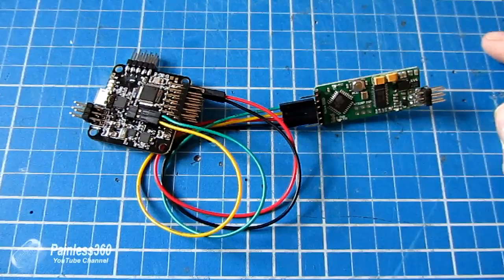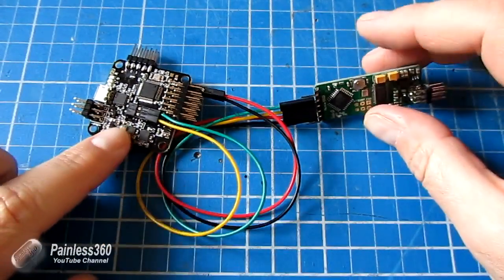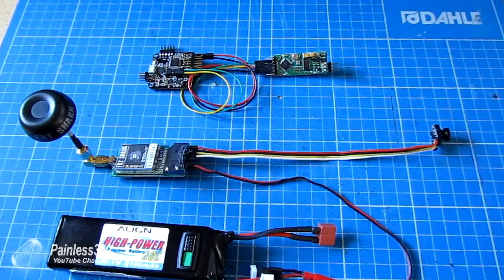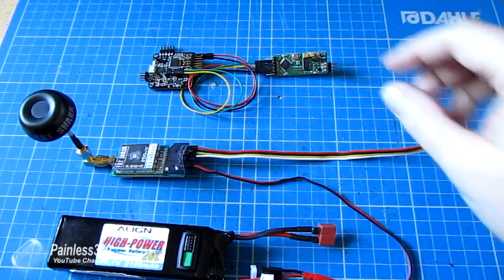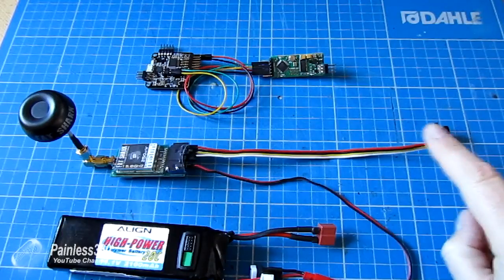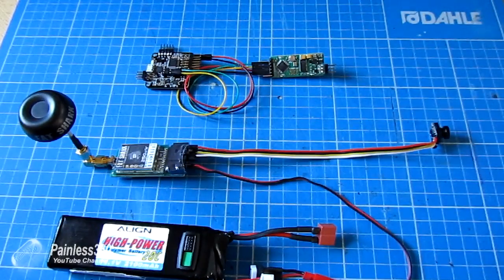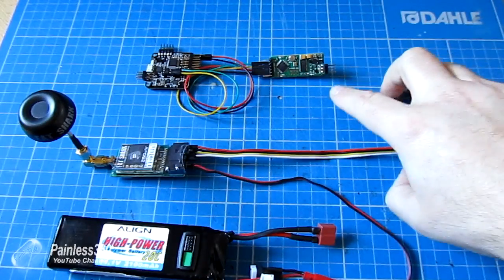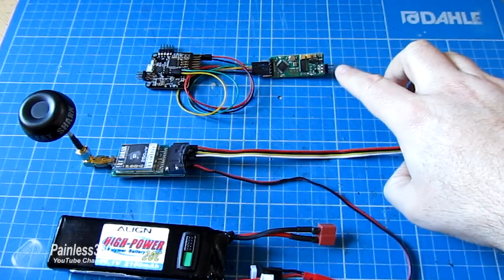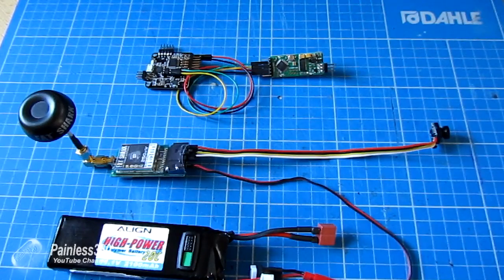Okay, now we've done that bit, we need to talk about how we're going to connect this all up into the camera. So the last part now is to connect the MinimOSD and put it in between the camera and the transmitter. That's relatively straightforward, but again we just have to be careful, as we know about from the power system, we don't put any voltages on these pins, just ground and signal.